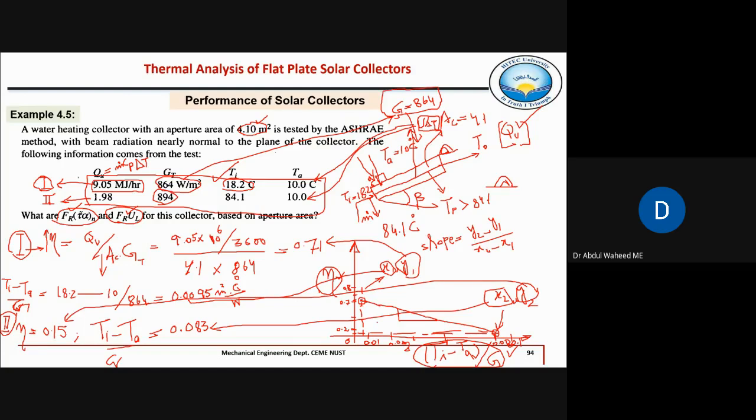So put it here, and that will be the slope, and slope represents the heat loss. Slope is dropping, so that will come out with a negative sign. The final answer will be with a negative sign because slope is decreasing. So that is 7.62 with a negative sign.